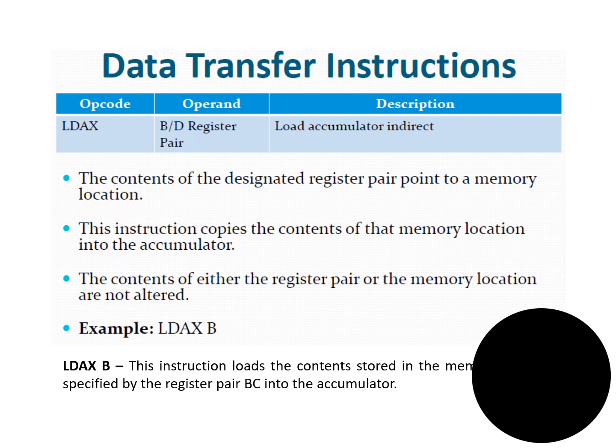So in this BC, for example, the address pointing to where your data lies is 4600. Now the BC register holds 4600, and consider that at this location the processor has a value of 15. It's 8-bit data that will be moved to the accumulator.